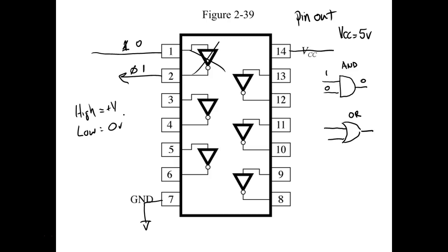We'll show you what's a legal high and what's a legal low. All I need to know is what voltage I should measure for a legal low, and what voltage I should measure for a legal high. Normally, it'll never be what you power up off of. If I power on 5 volts, my high will never make it to exactly 5 volts.